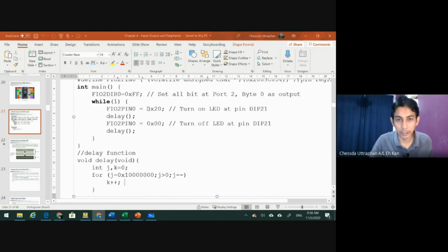So you can see the microcontroller is on here, and when you send 0 to this pin again, you can see the LED is turned off, and it will go back again and again and again forever. So this while(1) with brackets starting here and ending here means that your program will be inside this loop forever, until you switch off your microcontroller.